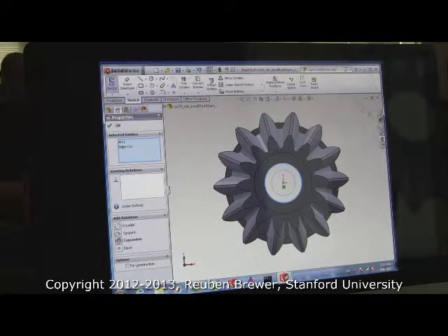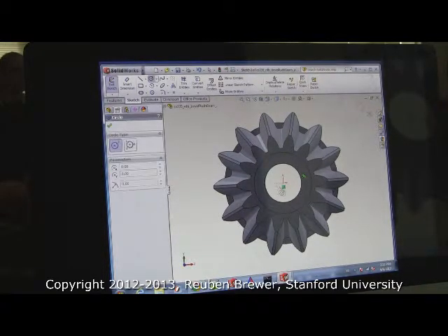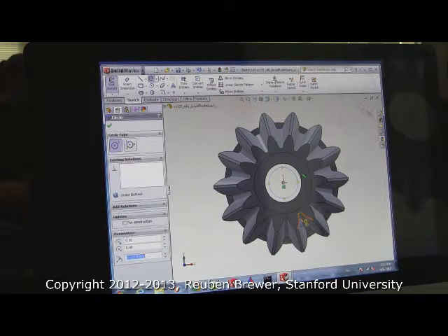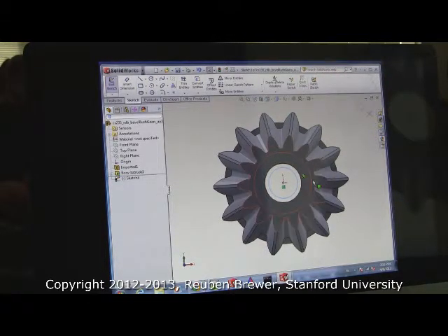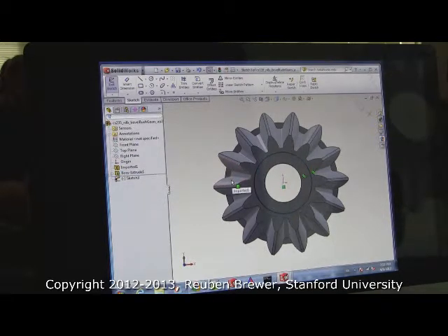Now in the bottom left corner, click co-radial. That means it's going to be on top of each other, the same radius. And now when you press escape, you see how the circles are on top of each other and it looks black? Now we're going to do that again. Circle, put it in the same spot. Now select that circle and you see this one right here in red? That one. Co-radial, and we're good. So before we extrude, everybody should have two circles that look like mine.